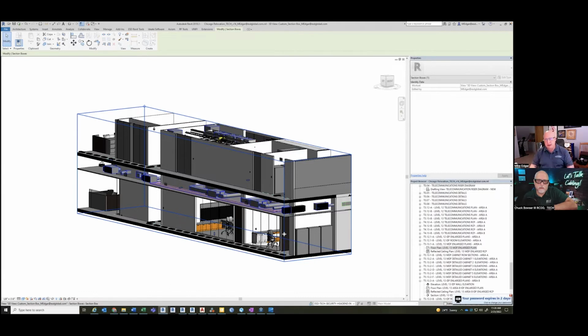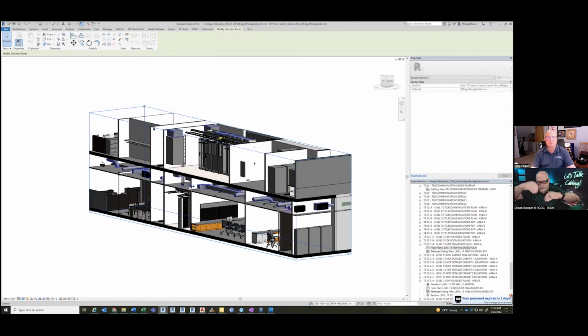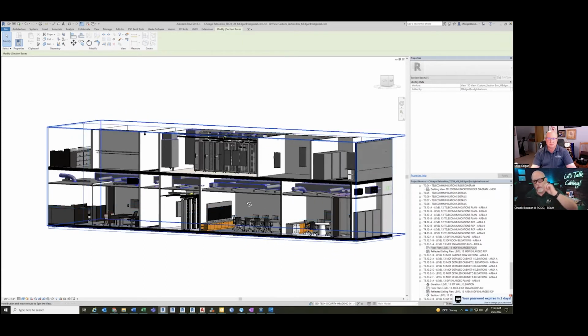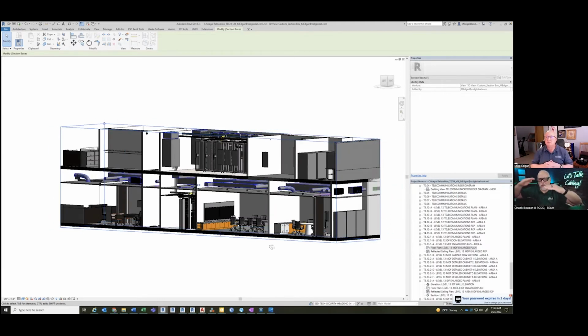And then you've got your guys in the field maybe standing around waiting. Make sure I understand, because again, I'm just a simple cable guy, right? When you say clash detection, that means when you open it up, because multiple people are entering in this, right? The low voltage people, the electrical, the HVAC, the sprinkler, and the drywall guys, and all that stuff. Here's a good example. The sprinkler guys are updating their Revit. If it comes through at the same height as our cable plant that we plan, it'll tell us that before we get in the field. Is that what you mean by clash detection?